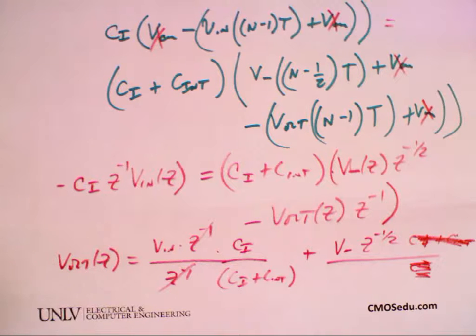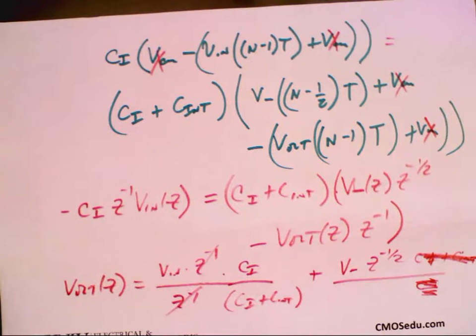How do I know that? Look at this, there's v out of z. How do I know that I've done it wrong? Well, there's no noise shaping, right? I don't see any integration or differentiation, rather, of the noise. So I'm missing a 1 minus z to the minus 1. So let me pause for a moment and see if I can figure out what I did wrong.